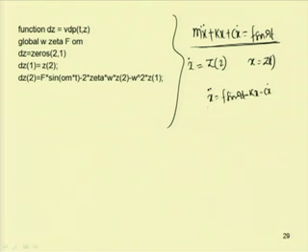So, this x double dot can be written as dz2 by dt, as x dot is z2. So, this is dz2 by dt, and this will be equal to f sin omega t minus k, for x one puts z1, minus c, for x dot one puts z2.